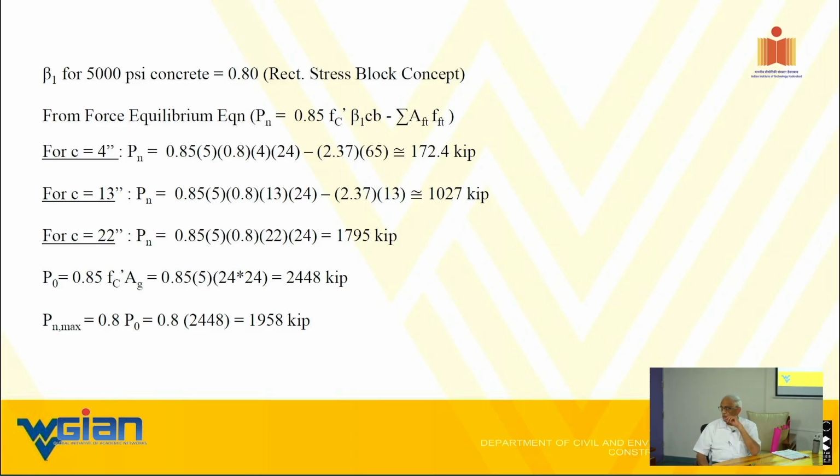So is there any limitation on the percentage of reinforcement? Of course. I told you 8% for columns, 4 or 5% or 6% for beams. 4%, I think. In the Indian code it is 4%. Yeah, same with us too. You don't want to exceed that.